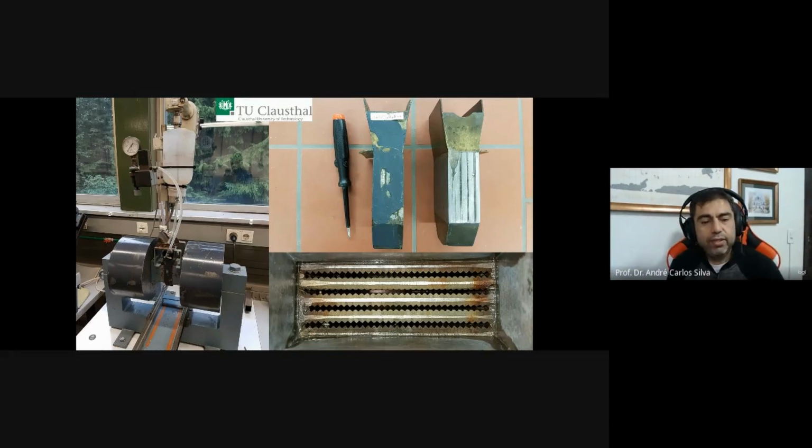And what I'm seeing over here is the Jones magnetic separator. And again, the name Jones. Why do we only talk about Jones? Because he and his company were one of the main manufacturers. And we have many different layouts for this, okay? But the magnetic matrix that I showed you guys before, it's right here. So this is the matrix, and that's the gap on the matrix.